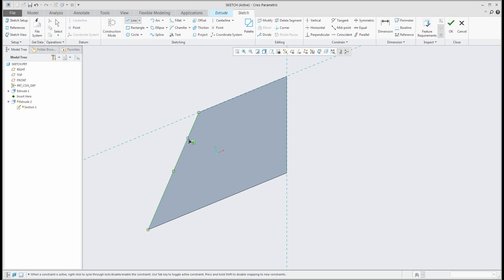You can see here, the system will automatically snap to the existing edge, and the system will automatically add this reference. Or you can use the Alt key and select the surface or edge, and you will add the reference on the fly. And you can follow and finish your sketch. For example, create standard lines. So here is the answer how to create references on the fly.